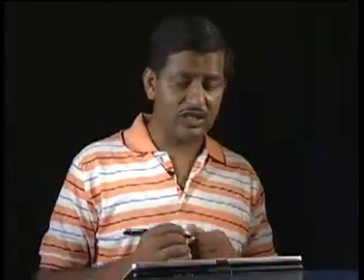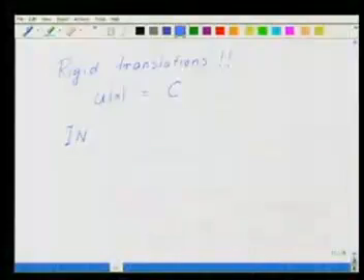That is, there is no other rigid motion which is permitted for this kind of a bar. So the rank deficiency of the stiffness matrix that we got is 1. Now the rank deficiency is 1, and we saw that our system equations are consistent, so a solution will exist. But the question is, here we will have infinite solutions.